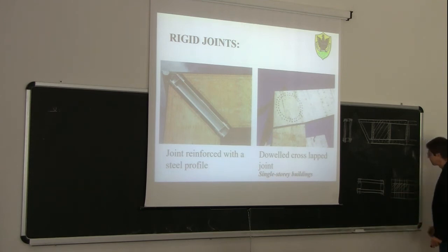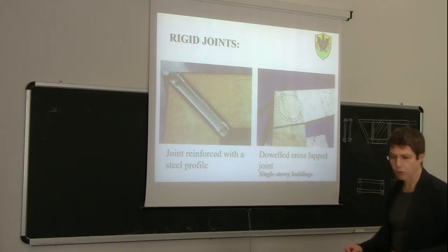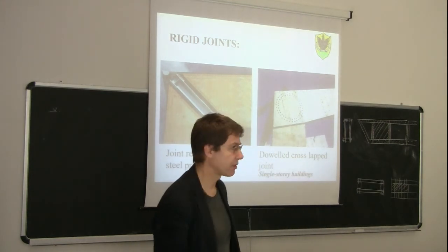So this is basically looking down at a situation like this. This is actually made of LVL, but could also be made of glulam. In this case, we have, as you can see, two lines, two circles of dowels. Note that at least 4 dowels, so 1, 2, 3, and 4, are characterized by having at the two sides some washers in order to ensure that these two parts will not fall apart.